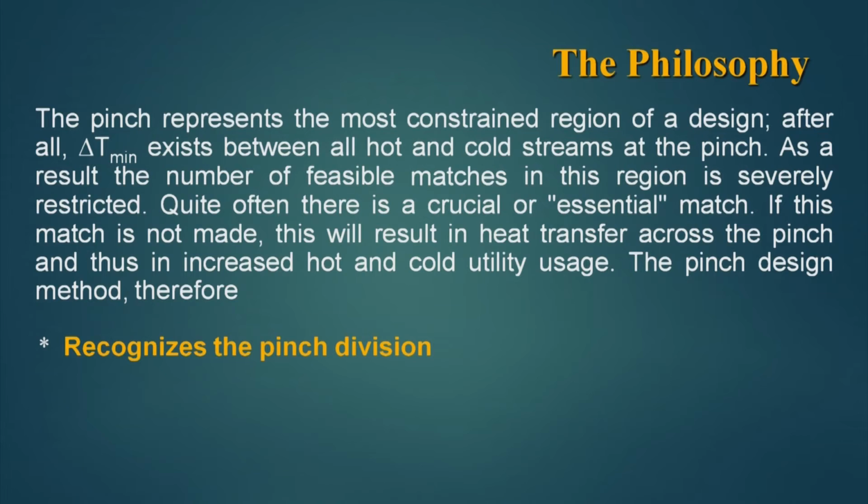That is why in the pinch design methodology, we always recognize the pinch division, because it divides a bigger problem into two smaller problems at the pinch, because there is no heat flow through the pinch. That is why the upper pinch area and the lower pinch area, or we call it the hot end and the cold end, are separate as far as heat exchange is concerned.